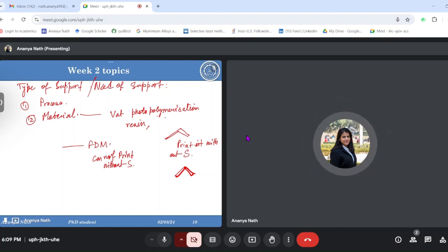It will need the support, but it depends on the material, because additive manufacturing process physics is all about how the material is interacting with the heat source, and how the material is getting deposited over the build plate. Every material has its own melting point, diffusivity, heat diffusion length, heat conductivity, shrinkage, solidification constant.